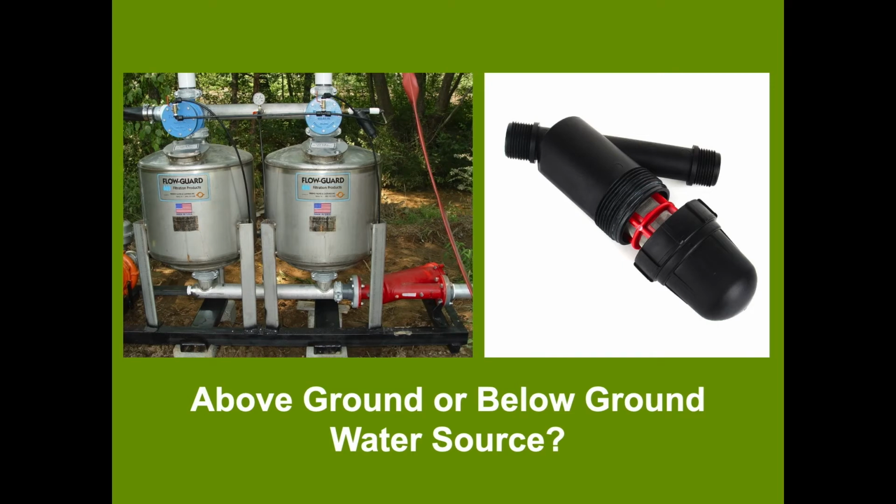Here's the water coming in. You force water to go through the filter. It's cleaned. Then you'll force water down this way, and it'll go out a port, and that helps you flush out all the particles that have accumulated in there. There's sand in there. There's going to be some screening and some pebbles, like river pebbles, that are smooth inside.